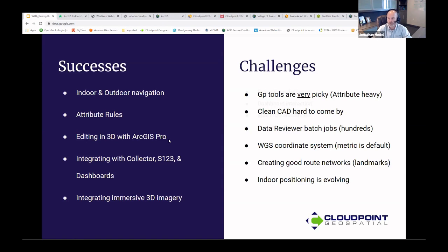And then the other challenge, of course, is that indoor positioning systems are still evolving. There are still different processes. We looked at that one slide, but the different systems are beacon systems, Wi-Fi systems, Bluetooth. But what I would recommend, if you're able to do it, of course it's expensive, is to utilize lighting systems. Now they have new lighting that is enabled for indoor positioning. And the beauty of that is you don't have to change batteries because they already have power fed to them. They are also the most accurate type of indoor positioning that you can get. So definitely something to recommend if you're exploring this.